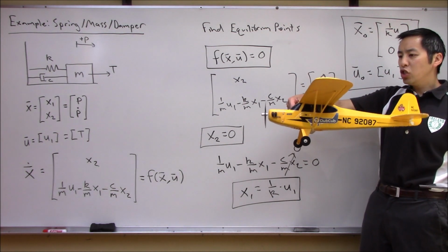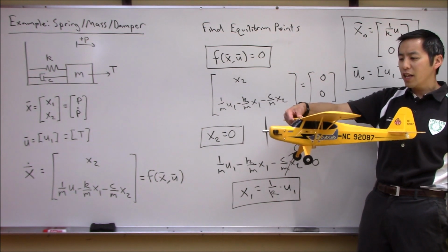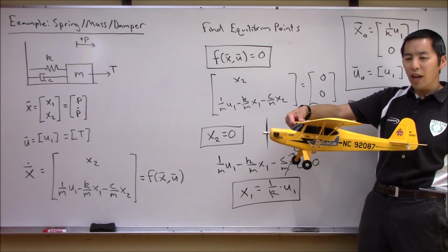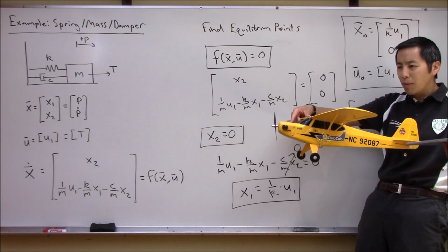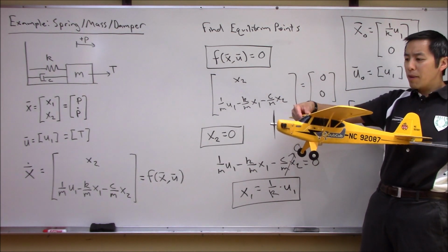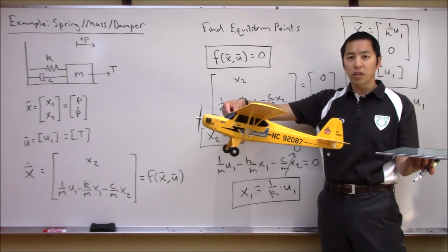They would jiggle the control surfaces. They might perturb the elevator a little bit, try to get the pitch motion stabilized, and do the same thing for the aileron. And if they're very careful with all of those control surface deflections, making small corrections and watching the results, they might eventually trim the aircraft into this condition, right?